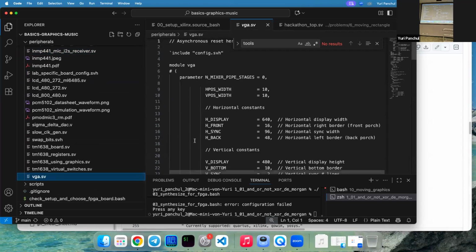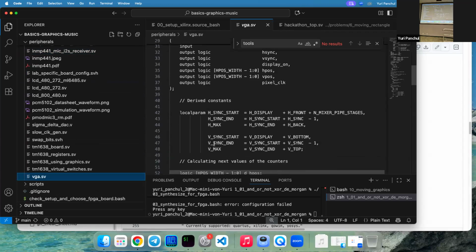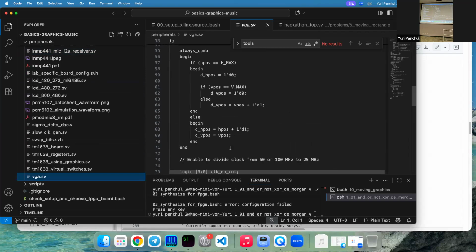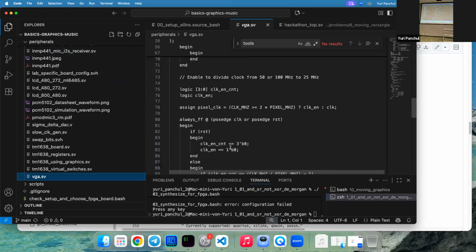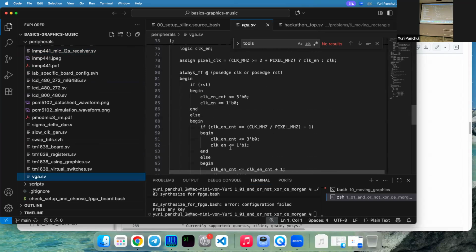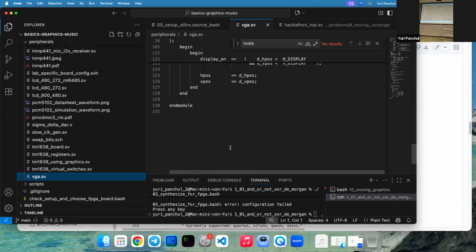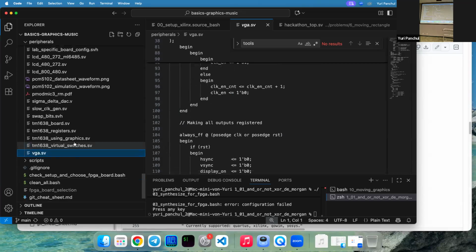In a VGA, all you have is essentially two counters, which just form the horizontal and vertical position. You send H-sync and V-sync signals to the VGA, and together with the colors for the pin, the VGA gets information about what it should draw in this place. The code here is very simple, similar to an LCD.